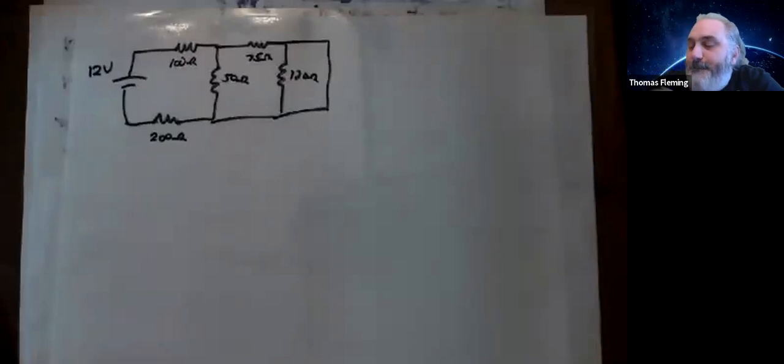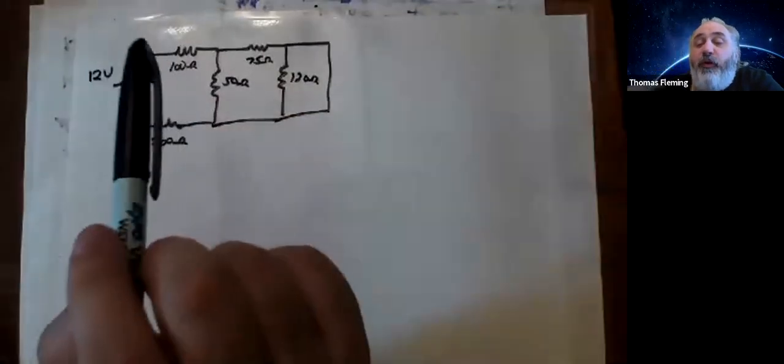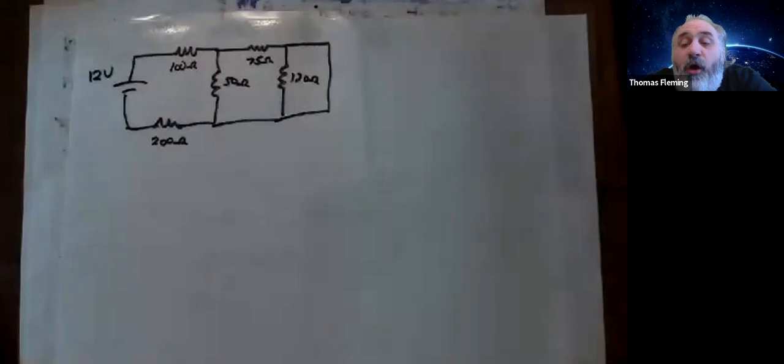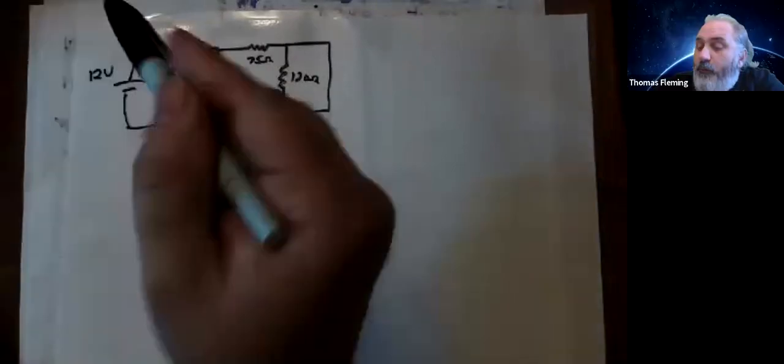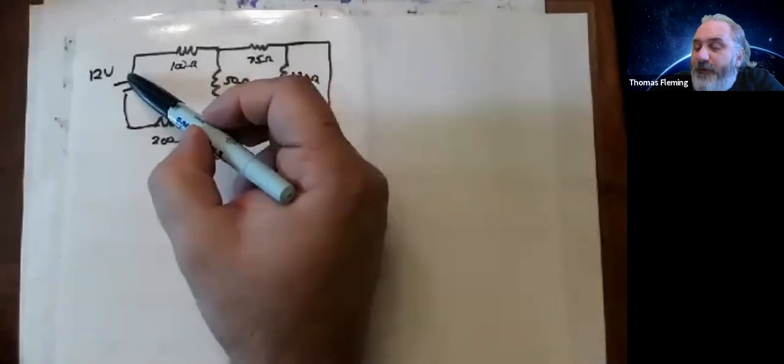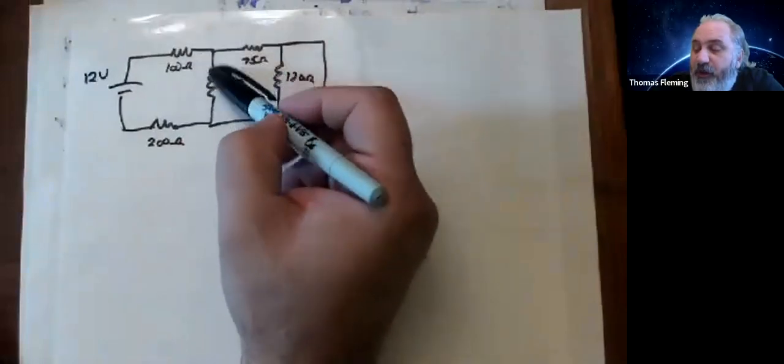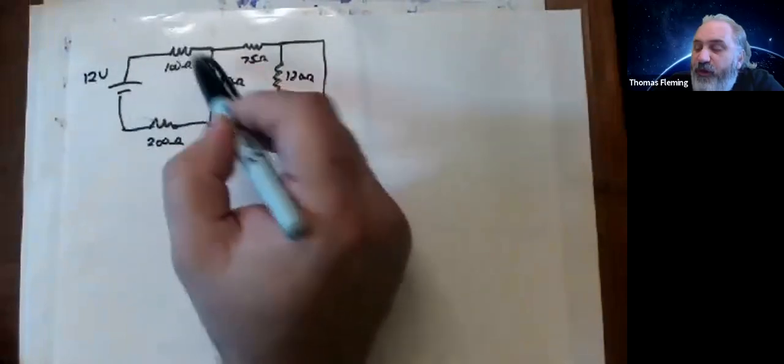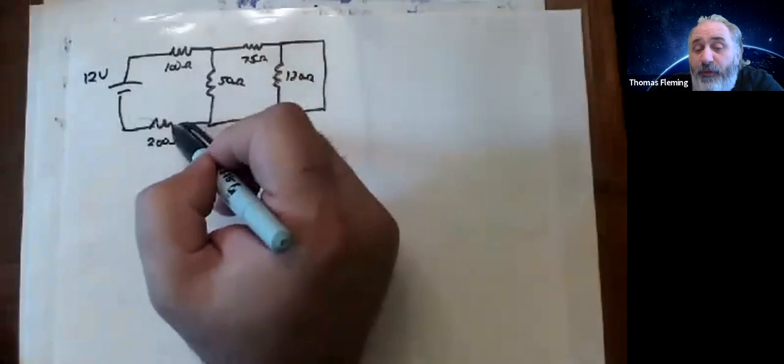Okay. So let's think this through, right? Do I have a complete circuit? Will there be any current coming at all through that circuit? Yes. Okay. So some of them will light up. So current's going to come out of here. It's going to definitely flow through this guy. It's going to get here. It's going to split two ways. Some current's going to go this way and this way and back. So these three would all light up because they'd all have current going through them.